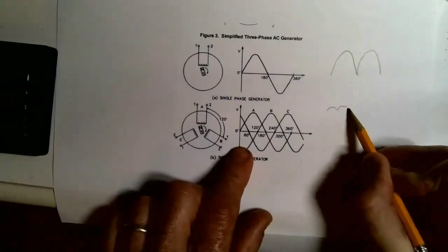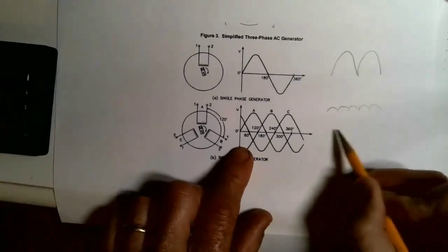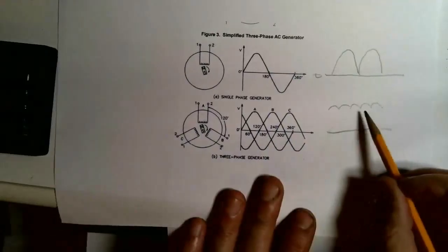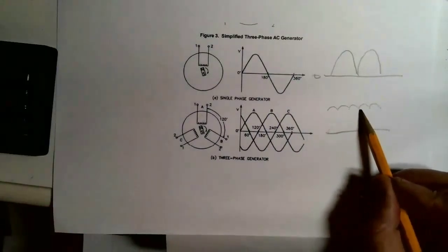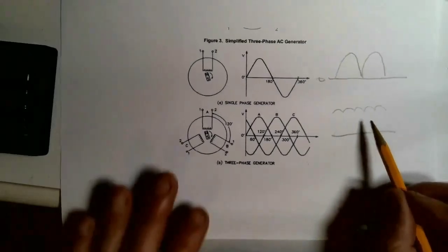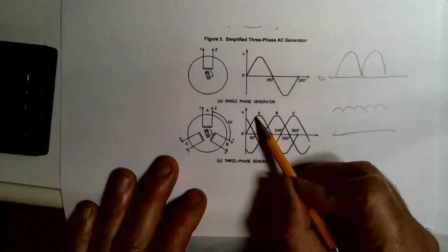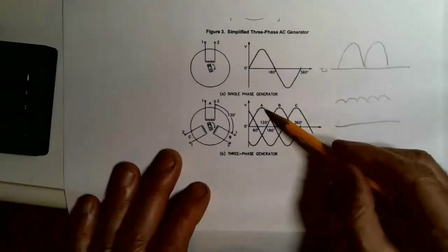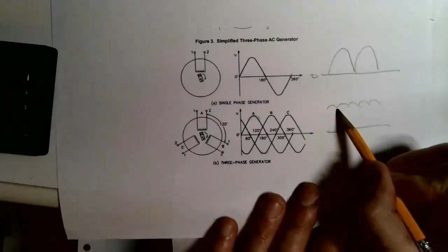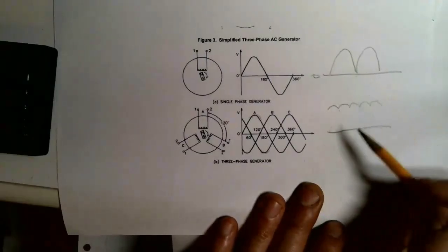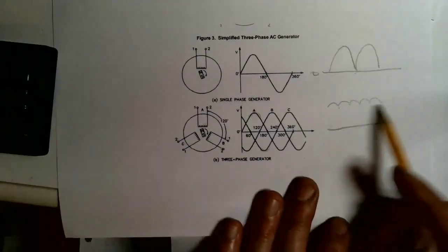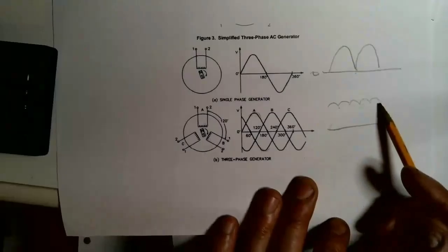this, where this is 0 here, and this is 0 here. It's almost DC without even filtering. And we only depend on phase A from here to here, roughly. And then next goes to phase C from here to here. See, the output doesn't drop to 0 like the single phase full wave rectifier does. It stays high. So this is much easier to filter or not even filter at all.